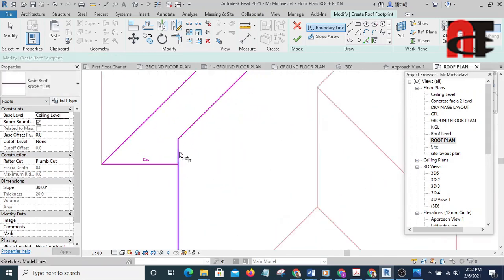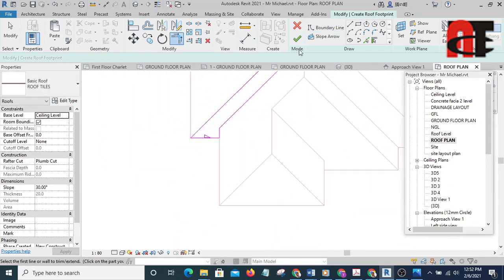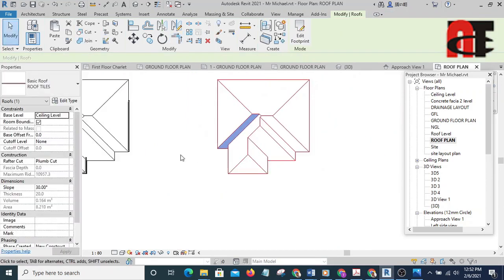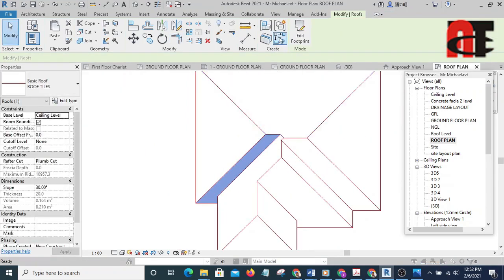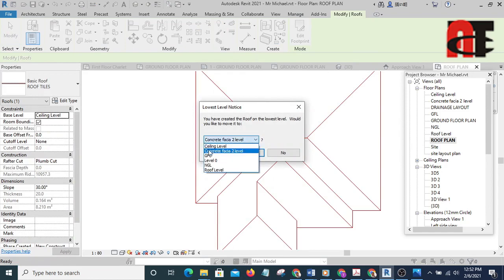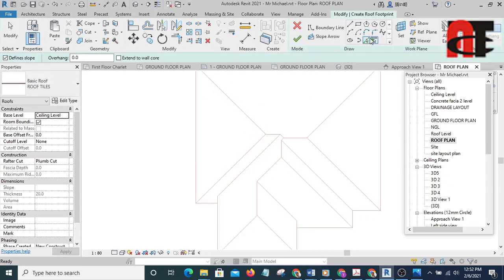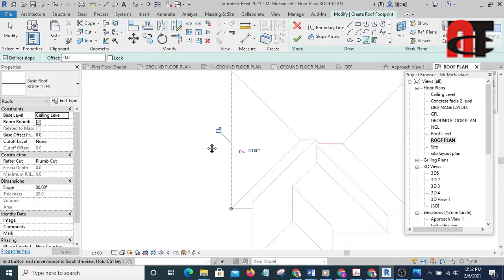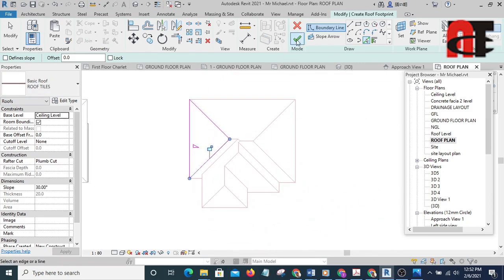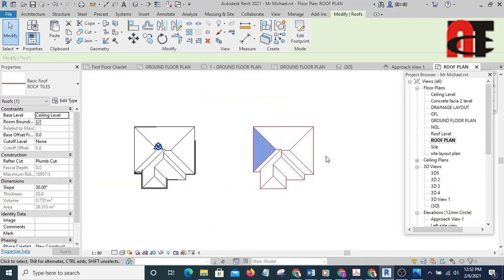Then let me trim this. I'll hit save. Then I'm going to create similar. So select my level. Yes. Then I'm going to pick line. This one should be defined. Then the remaining one will not be defined so that it will fall to one side. I'm going to hit OK.